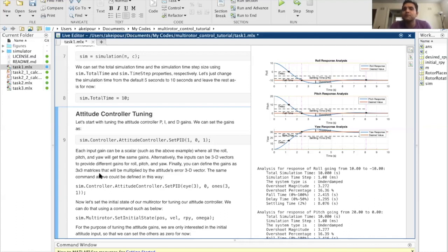It's very important to see how tuning works. So when you are doing actual tuning on your robots, you have some understanding of how it will look in reality. If the robot suddenly starts doing weird stuff, you have an idea what is happening: oh, I need to reduce this gain then.